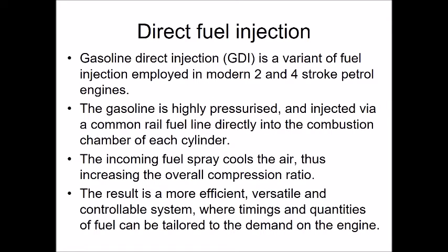So we're going to expand this a little bit into something called direct fuel injection. Now, the reason I'm teaching this is because pretty much every automobile that's being produced has certain emissions regulations to meet, which you're going to learn about a lot later on, in subsequent years and subsequent studies. One of the good solutions to getting around some of the emissions problems we have is to use something called GDI, which is gasoline direct injection, where we don't use a carburetor, and it's almost like a cross between the gasoline engine and the diesel engine.